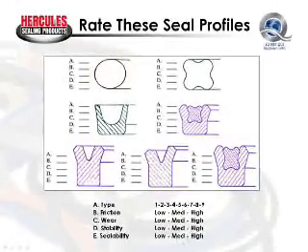So giving us a sealability somewhere in the medium or high medium range. This seal would be very good to replace a dynamic O-ring seal, where you had an application where the O-ring was not stable enough, was not performing satisfactorily. You could use a square seal like this.